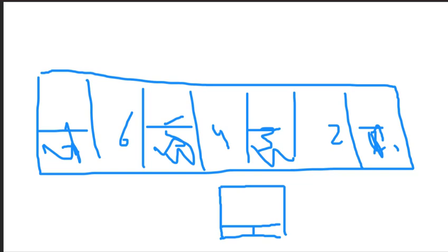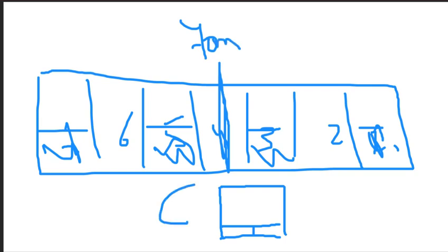Then the question is, calculate the bending stress diagram at mid-length, meaning you're located here in the middle of your vessel, mid-length at 70 meters. For this cross-section at that location, what is the stress diagram? How do these stresses evolve? I'm not talking about shear stresses in this case. I only ask you to focus on the bending stresses, compressive and tensile. That's the question. How do they evolve?